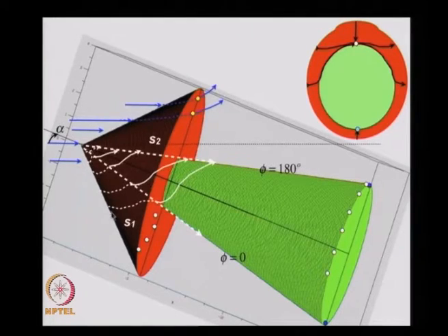So the streamlines which are generating from the bottom or the windward side of the cone and moving up on the surface of the cone are encountering an entropy S1. So all these streamlines that you see here have an entropy S1, an entropy change of S1 as they go here. And these streamlines go ahead and converge on the top.